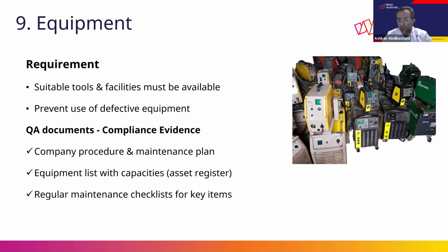That's the responsibility of the fabricator to provide the procedure, because when you get your ISO 3834 certification, for example, in compliance with Part 2, in your certificate you don't list the name of the client. You just list the product type. We list the product standard. We list the welding standard, welding process, material groups, and welding coordination team.